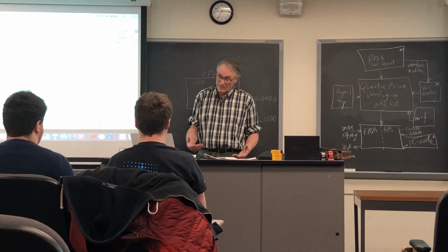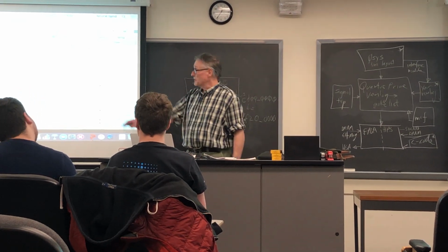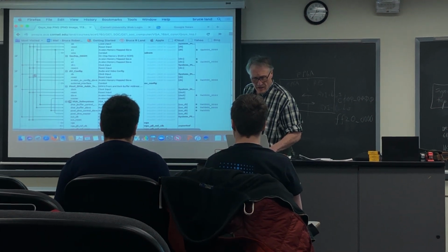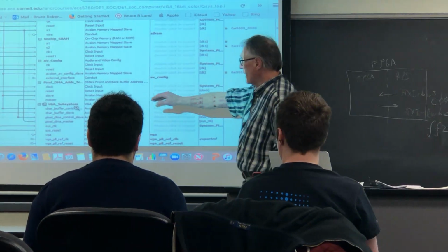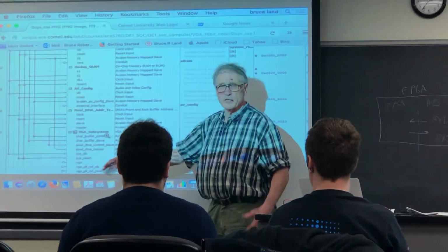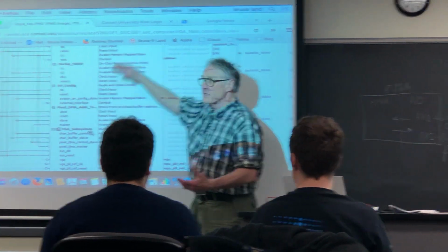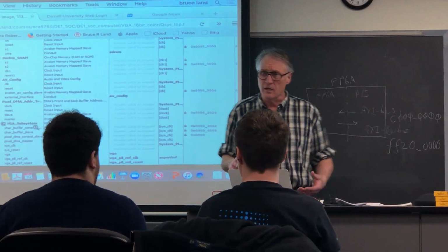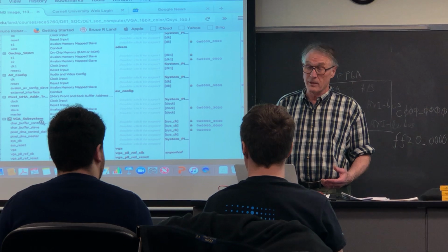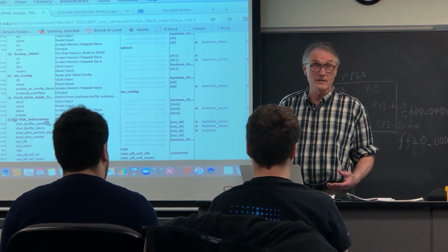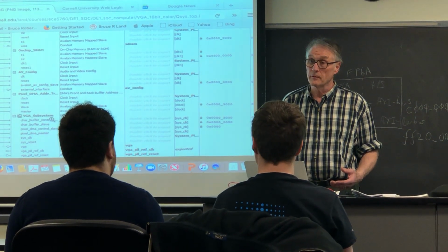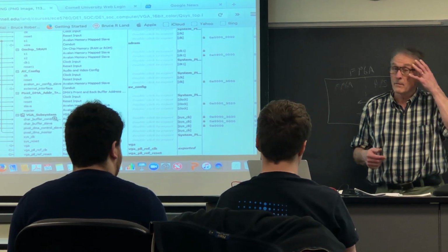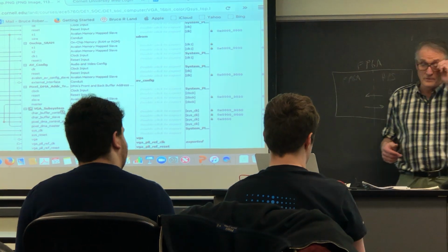It is really complicated. And the top level is only the beginning. It turns out that the VGA subsystem has another set of modules internal to it that is as big as this and has the most obscure settings you have ever seen. I read the manual. I read the manual 10 times. If I hadn't had an example, I never would have gotten this set up. Don't start from scratch, folks. There's too many variables.